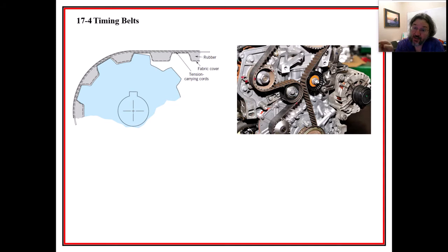Because by doing that, they're able to shift and change when the valves open and close and when the fuel injection might take place. So for an example, in diesel engines, they have a fuel injector as opposed to having a carbureted intake. That is that the air comes in clean in diesel, and then fuel is injected directly into the cylinder at a particular timing